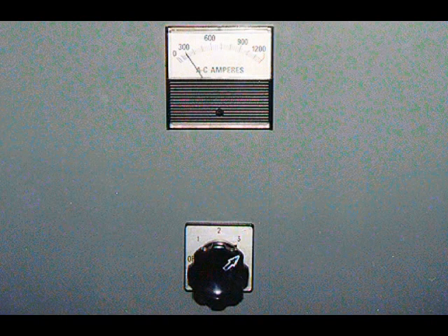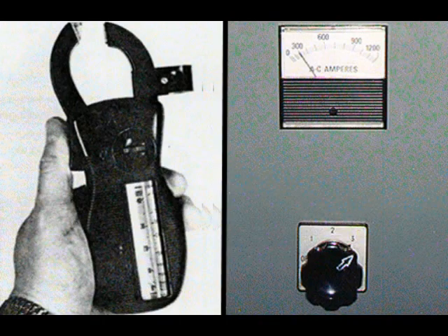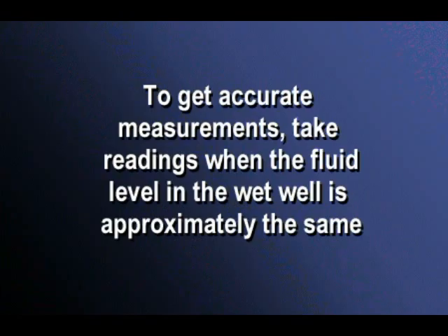First, the measure of power drawn is usually taken in amperes, the units of current. The voltage delivered to a motor is usually constant, but should also be monitored. Operators should be able to take amperage readings of all pump motors in their plants. Permanently installed ammeters should be continuously measuring current, or a portable ammeter should be available to regularly check current. If pumping from a wet well, the difference in water level between the full and empty wells will affect amperage readings. A good time to take amperage readings is a few seconds after the pump in the wet well starts.